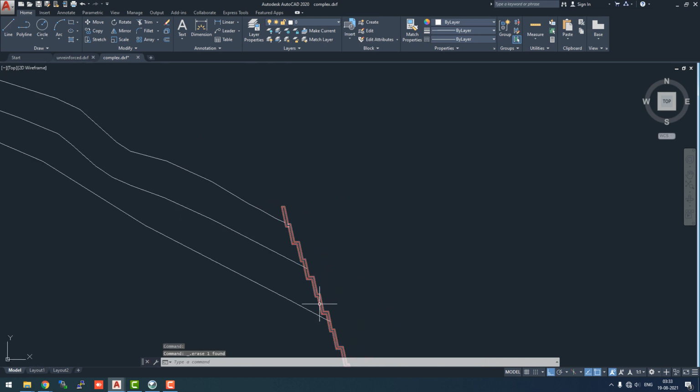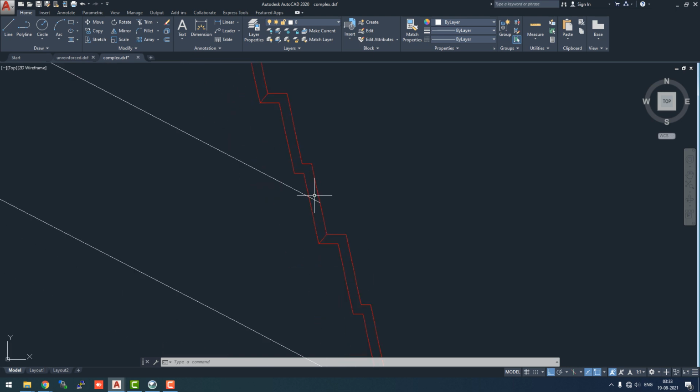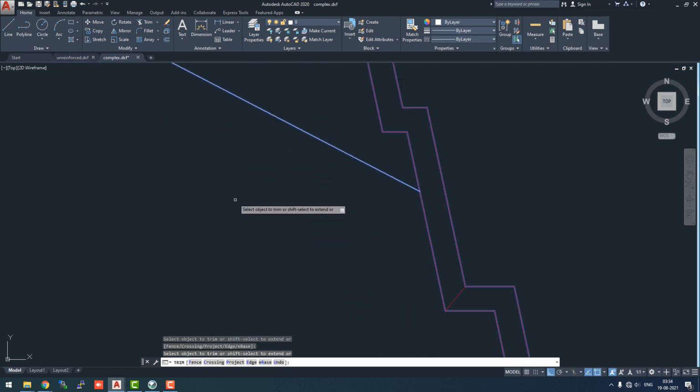And if we see anything else, yeah, here there is more and more fine tuning to be done on the sketch. We'll again trim. Oh, sorry, we'll again click on escape first, and we'll again trim using selecting these two objects. Now clicking on enter and removing the part which is trimmed.